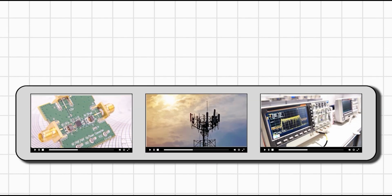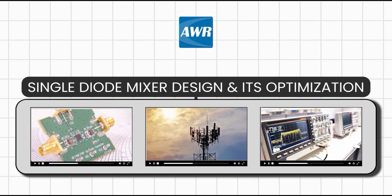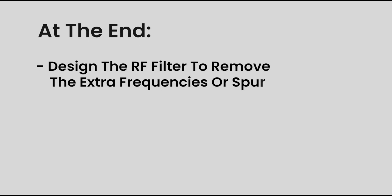This is a 3-video series on single diode mixer design and optimization using AWR Microwave Office. In this video, we are going to simulate the mixer circuit and optimize the output spectrum by changing parameters, and at the end we are going to design the RF filter to remove all the extra frequencies or spurs.